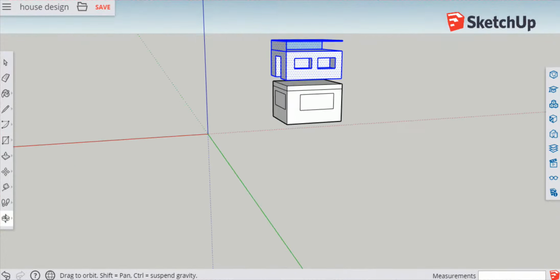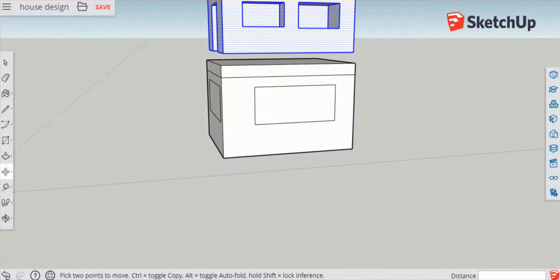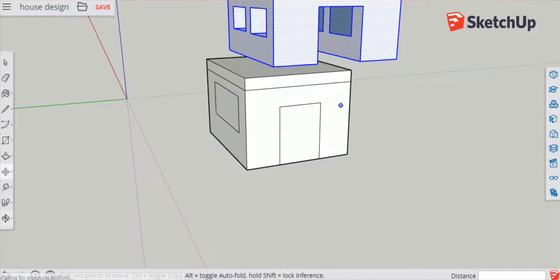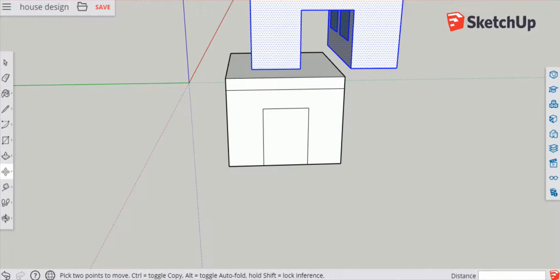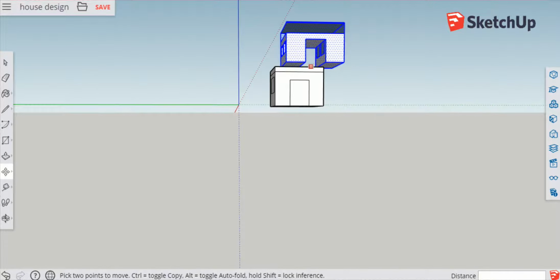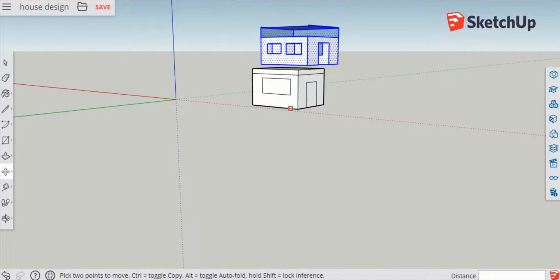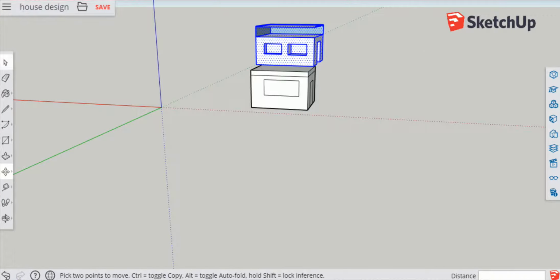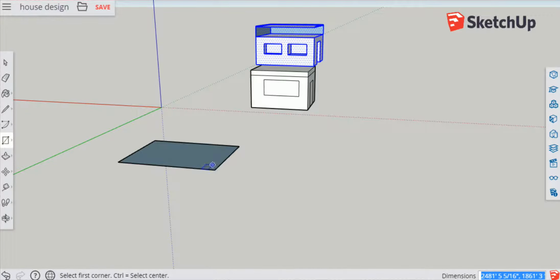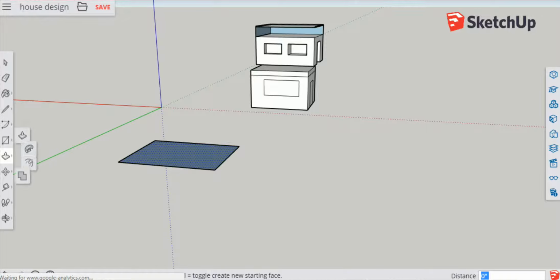The thing is, you see, I'm not actually attaching them, because once you attach them, what happens is the SketchUp things become a single face. For example, I'll give you an example here right now. So let's leave that for now over here. Let's draw another rectangle to understand better how things are working here, and then we use the push tool.